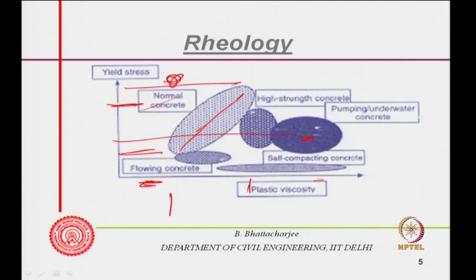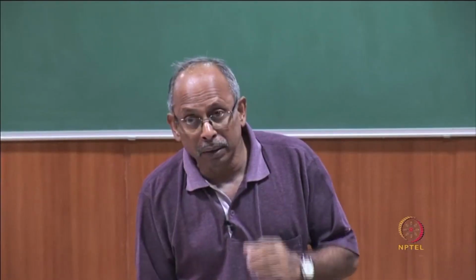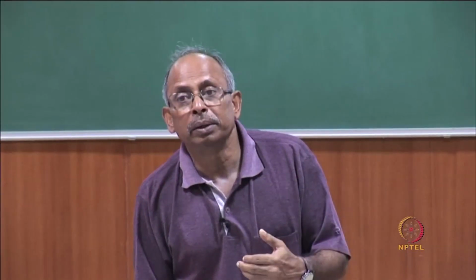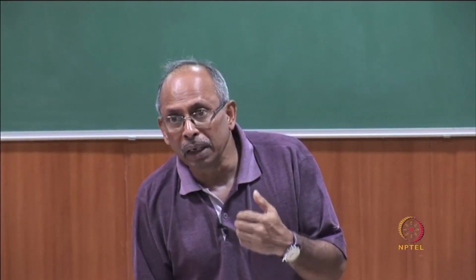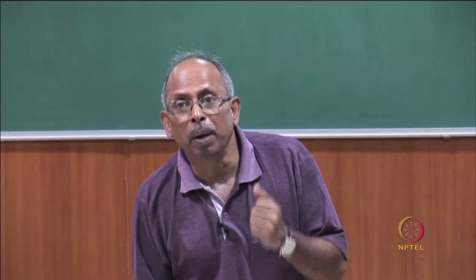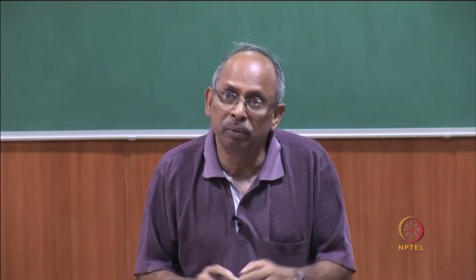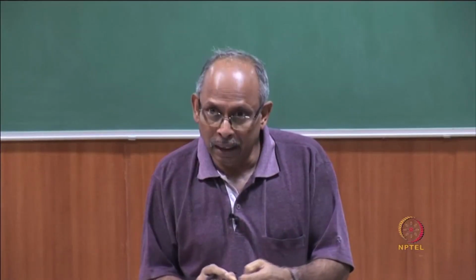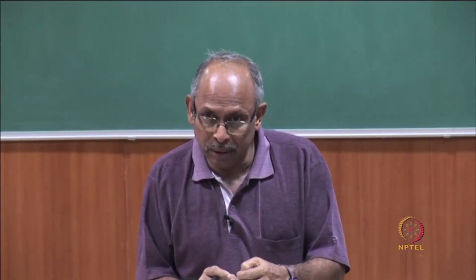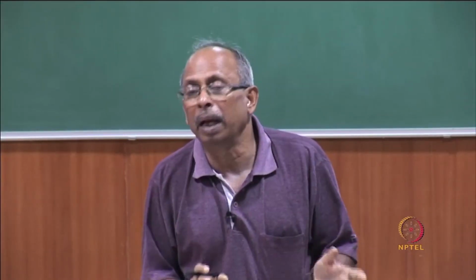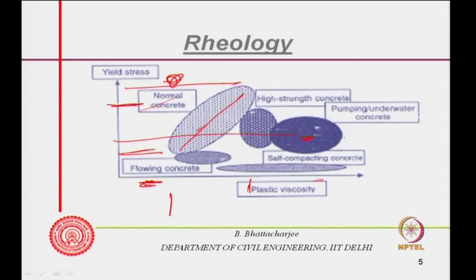Now, it can withstand some amount of yield shear stress because you will be pumping it. So, there is a pumping pressure, only thing it should remain cohesive and should not segregate. Disturbed relative motion between particles should not be there within it, but it must form a plug and then move. So, that is pumpable concrete.